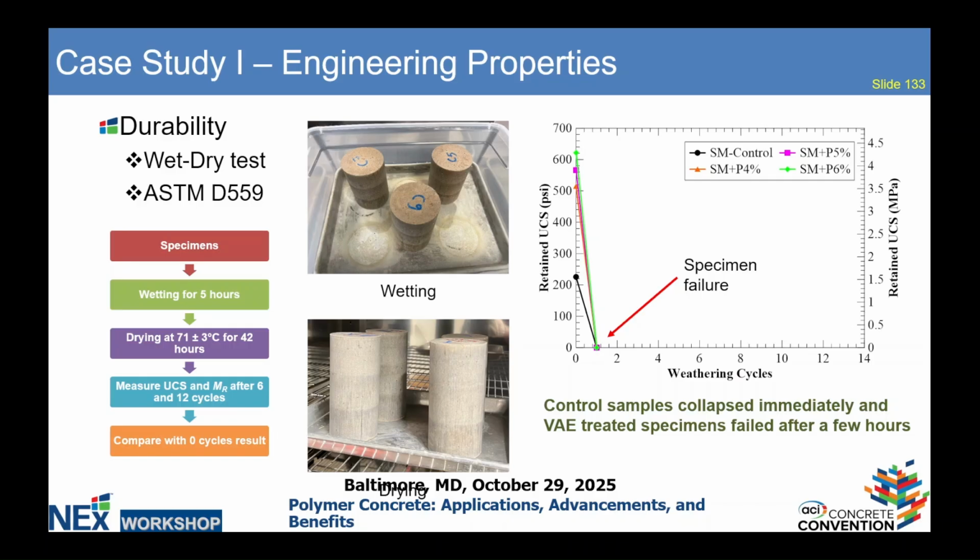...which likes water and reacts with water. And also we find for many other stabilizers, they actually will fail this criteria. Even if you use all the DOT recommended cement or lime dosages, they'll fail just because the method is such an extreme scenario. You expose the material to 100% moisture, and then right after that, you dry it to really high temperature, and it's kind of a torture to the specimen. So that's the one part.